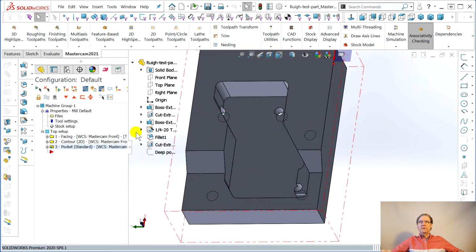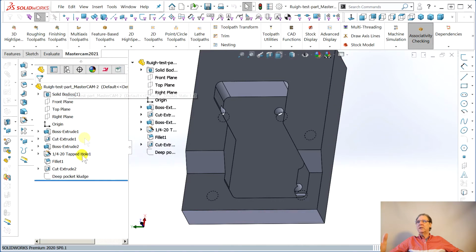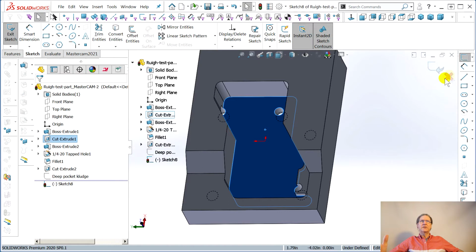I'll save you trying to make it do what I wanted and trying to find some way to adjust toolpaths. We had to do this in all the other programs, so let's do it here too. We'll just go to here, select the bottom face. We will make a sketch. While that face is lit up, we'll do our convert entities magnificence.